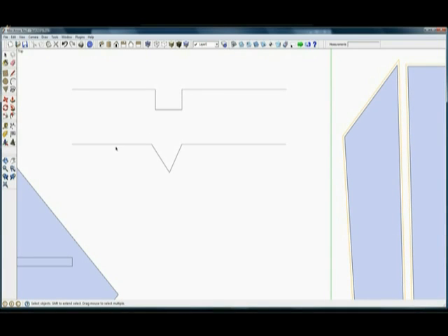However, if we use a V-tab configuration, the machine is always in motion. It never stops, and that can add significant time savings to your cut file. Doing 2 of these mini arrows on my MK2 machine, processing at like 400 inches a minute just to prove it, and then changing all the tabs to V tabs, I improved my time from, I want to say like 6 minutes down to about 4 minutes to cut 2 of these airplane kits out. So there's time savings there.